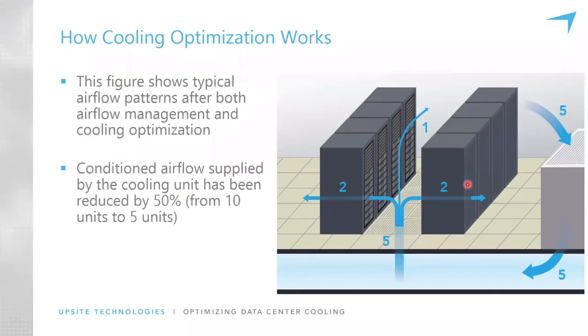We now have the ability to reduce fan speeds or turn off half the cooling units in the room and realize those benefits. We'll turn it down not all the way to 4, but to deliver 5, have a little extra conditioned air, to have a little buffer for variations in IT demand and slight positive pressure in the aisle. But now from an airflow volumetric flow rate perspective, the cooling has been optimized.